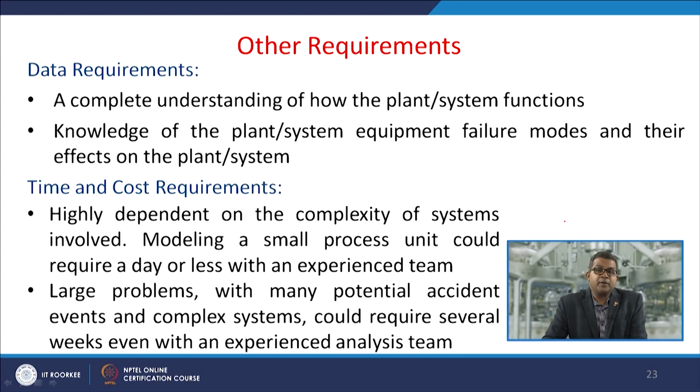The data requirement: a complete understanding of how the plant system functions is the utmost requirement for this system. The knowledge of the plant system equipment failure modes and their effect on the plant or system is quite essential under the head of the data requirement. The time and cost requirements are highly dependent on the complexity of the system involved.